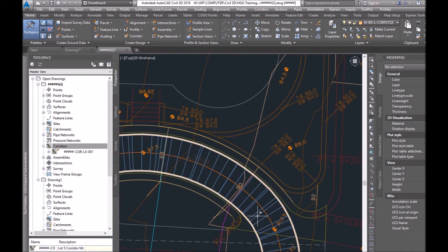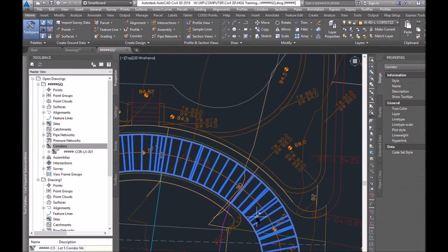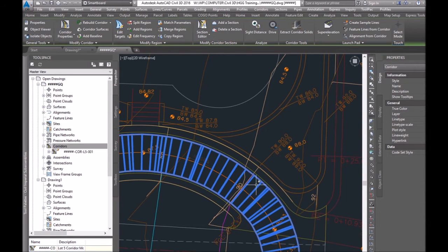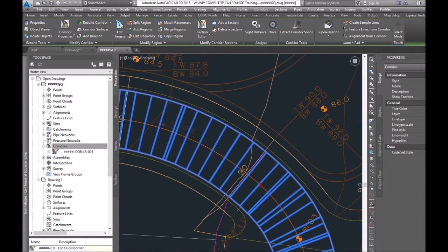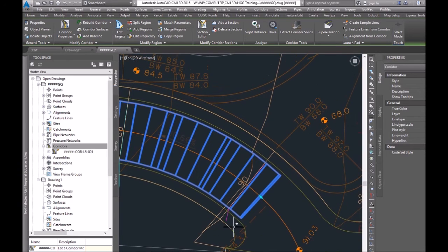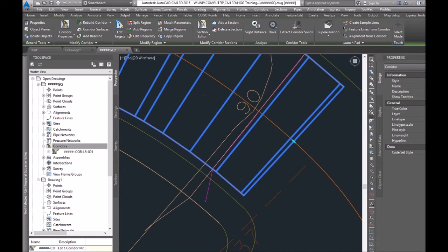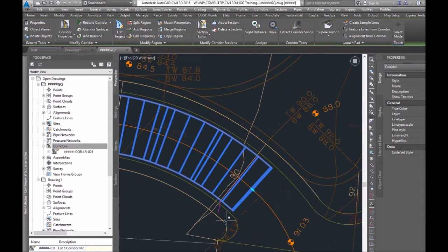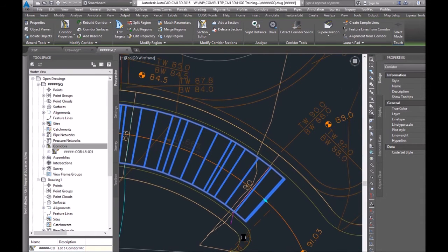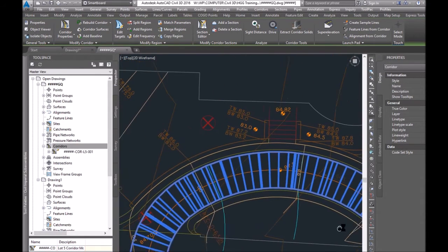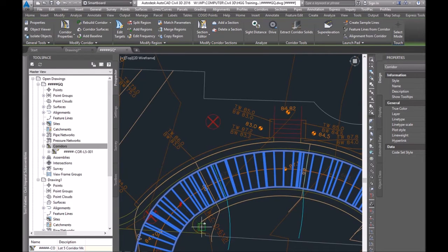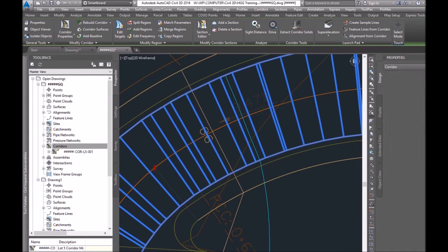So the next thing I'm going to do, just for this driveway, now that we have these as the width targets, there's this little arrow here. I'm going to slide it over here, and it's going to start right there. Because the return's going to be over here, it's going to be kind of complicated, so I'm not going to worry about it right now. It's going to start right there, and this one is going to end right here.